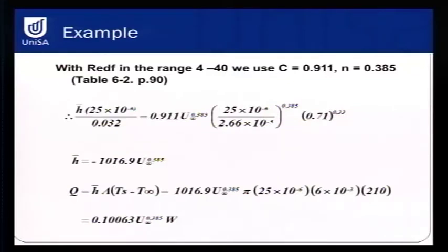This equation enables us very quickly to find the value of U regardless of the velocity. So we measure Q and we use this equation to find U infinity, the velocity that we're looking for. From a digital measurement of our current, and voltage is usually constant, we can work out U infinity, and that's a lot easier than the other physical direct measurement of velocity.